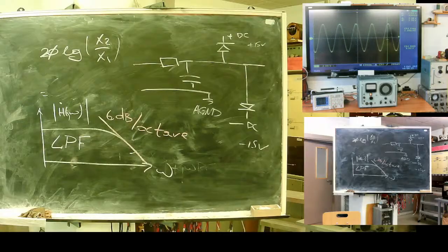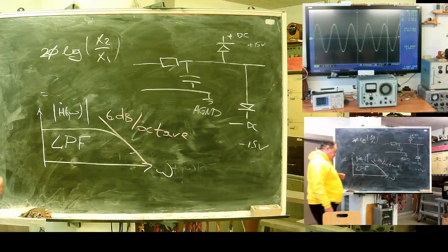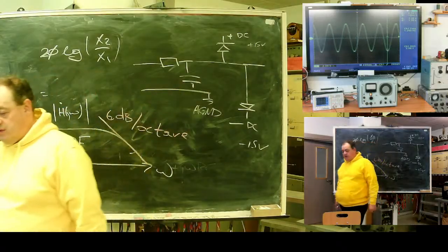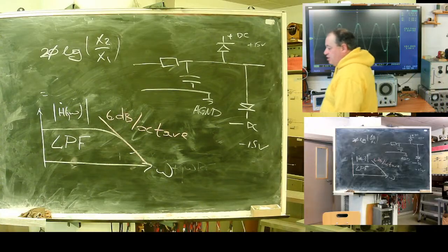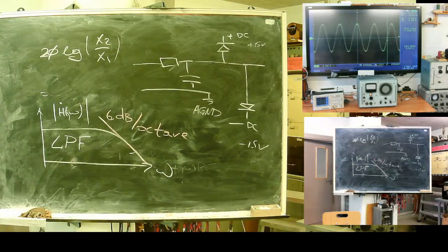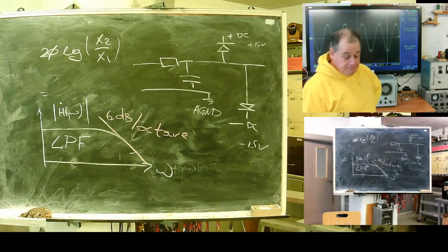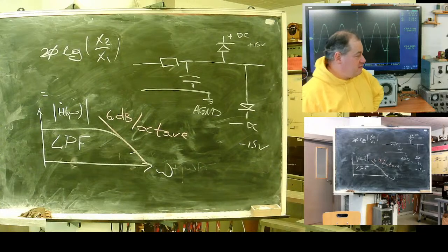One of the problems of such a simple filter: capacitors do have drift in their capacity with temperature. It brings imprecision, but more of a real problem when you need uniform performance in the frequency range without distortion. Besides these problems, such a low pass filter brings angular shift also. Yes, it brings angular shift. It's not always allowed.